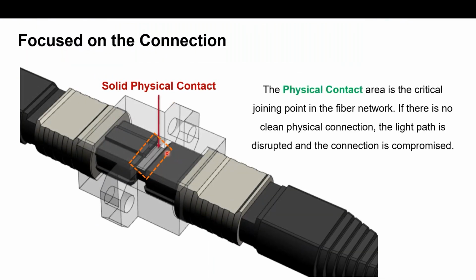So the whole key to those pins is, if you tried to mate an unpinned to unpinned cable together, even though you're putting it in this coupler, there's no way you're going to get all 12 of those fibers to align perfectly. That's where those alignment pins come in. It's going to match up all 12 or 24. If you've got 24, even more difficult, all of those fibers from one cable to the other.